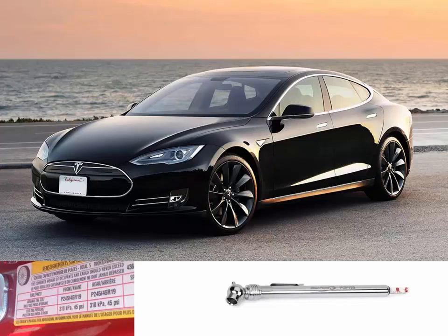It pushes the little thing out. There's probably some sort of a spring in there that provides resistance, and it only goes out so far as the pressure in the tire. But actually, the air that's surrounding this device has an effect on the reading that it gives. It's not just the tire pressure, but it's also the atmospheric pressure that affects the gauge reading.